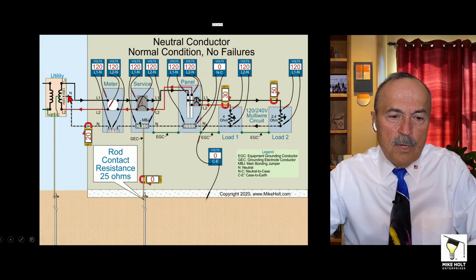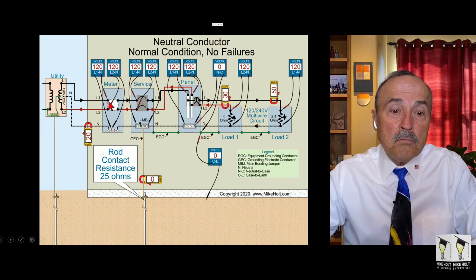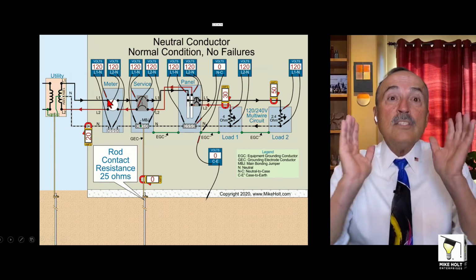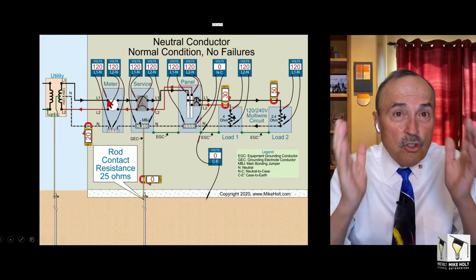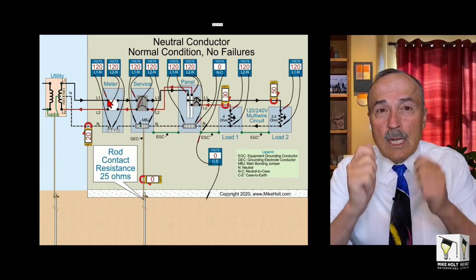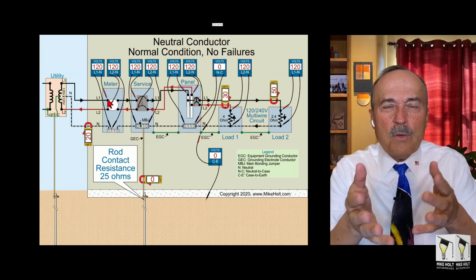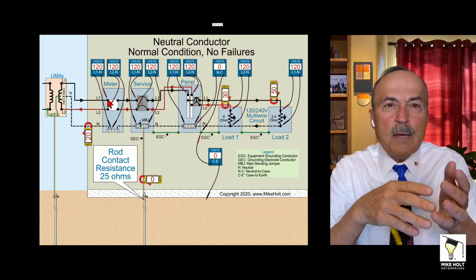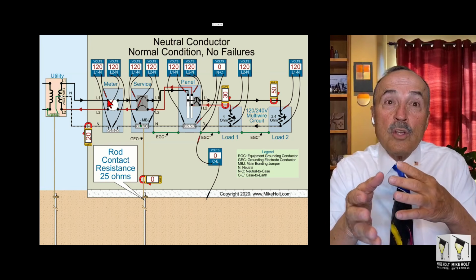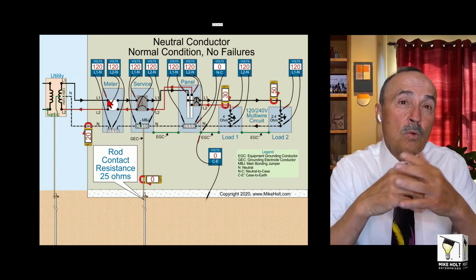Okay. Then you bring your two-phase conductors and a neutral, and you go on the line side of the meter. So let's just assume you're going to a job, and you should be able to do this. You go to the line side of the meter, line 1 to the neutral. Now, it's never going to be 120. It might be 123, it might be 117, depending upon where you are in the distribution system, what time of the day, what the loading is going to be. Basically, it's going to be about 120.